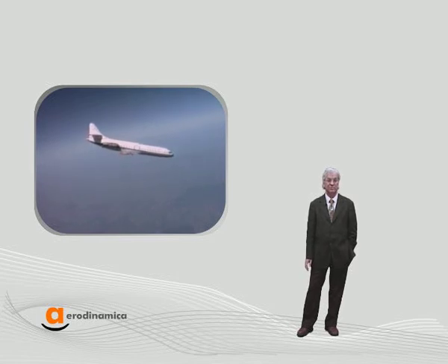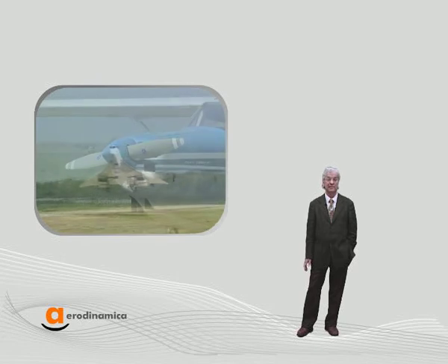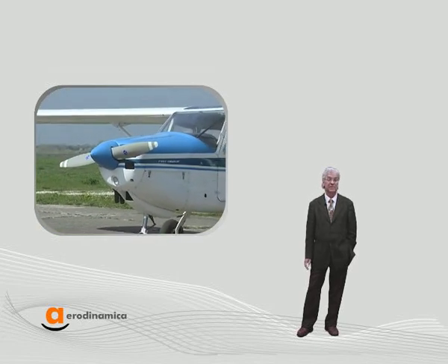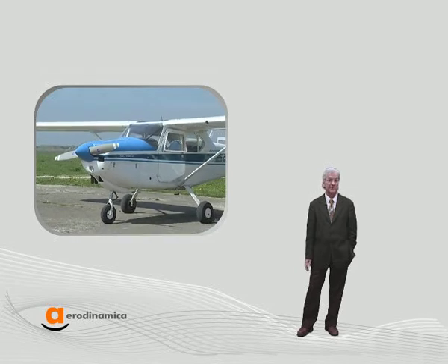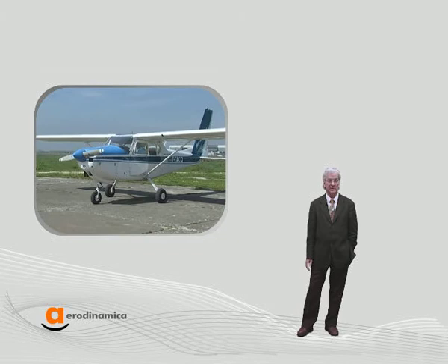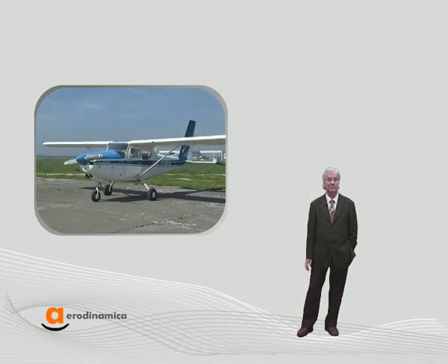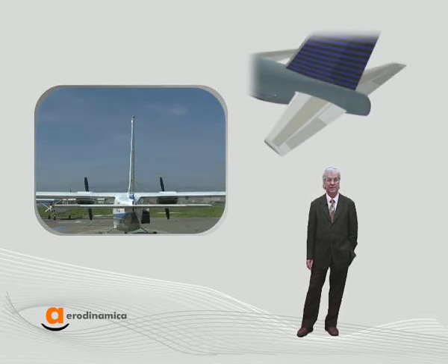They constitute a disturbance. How can we contrast them? Does the pilot always step in? No, it's a burdensome task for him, especially during a long flight. In addition, these phenomena are so fast that the pilot is not always able to contrast them. For the vertical gusts, the stabilizer has a stabilizing role. For the lateral gusts, the fin has a stabilizing role.